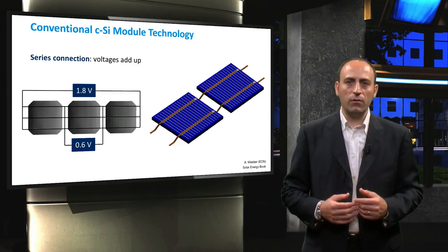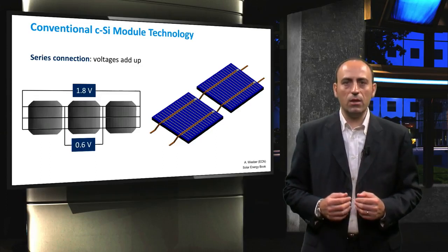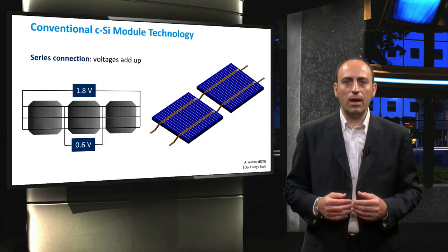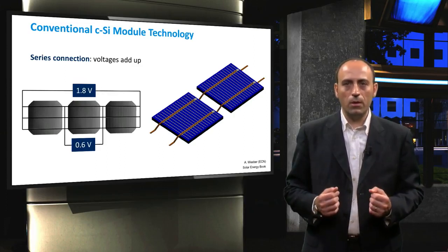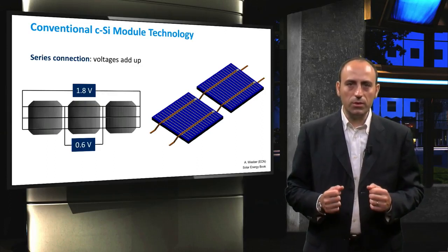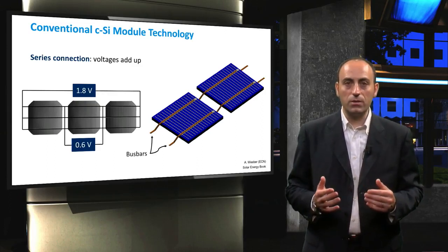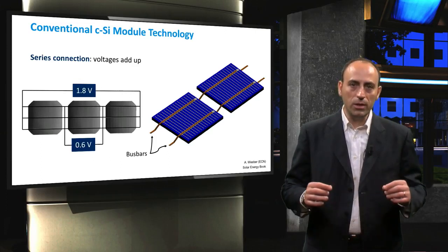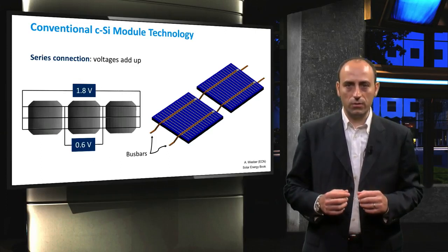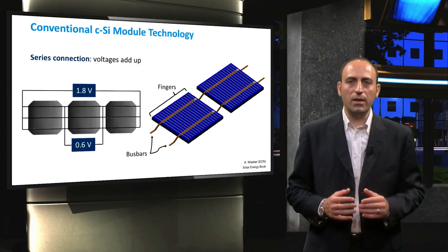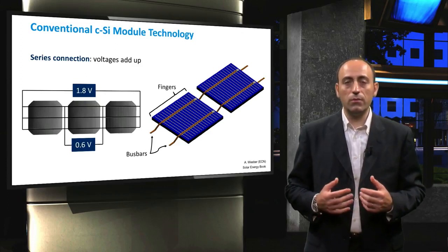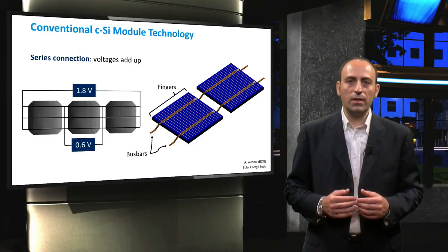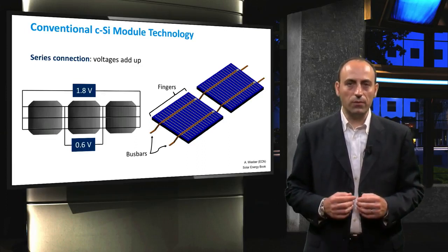At the front side of a conventional crystalline silicon cell, we can usually find a silver-based H-grid, named after its particular shape. The two widest metal strips printed on the cell, also called bus bars, represent the arms of the H, and the other perpendicular thin lines are called fingers. On the rear side, a fully metallized area is usually realized. In case of bifacial PV modules, the rear side does have a second H-grid.